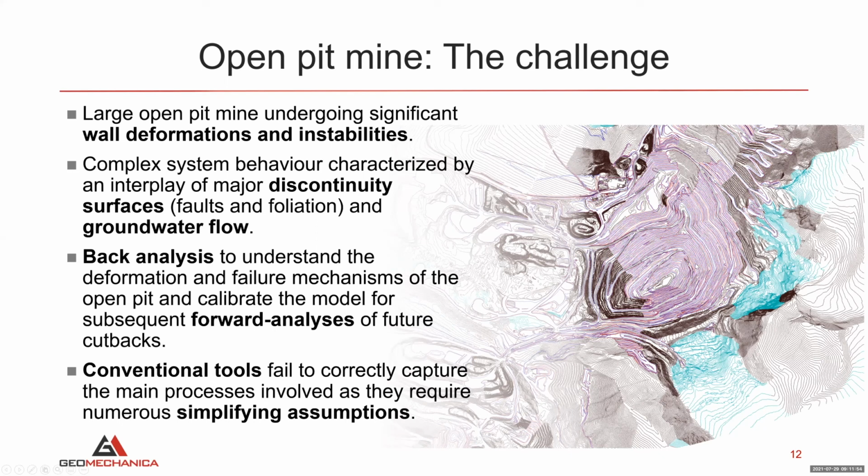The system behavior was very complex and characterized by an interplay of major discontinuity surfaces, including faults and foliation, as well as groundwater flow. Our first task was to back analyze to understand the deformation and failure mechanisms of the open pit that were observed in the past, and to calibrate the models for subsequent forward analysis of future cutbacks or pushbacks.